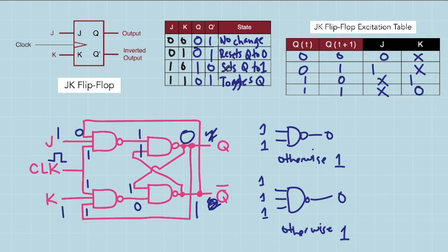One thing to note here is that JK flip-flop solves the problem of SR flip-flop, wherein if you supply set and reset with a simultaneous 1, this will be an invalid input, but JK flip-flop tries to interpret this as a toggle command.